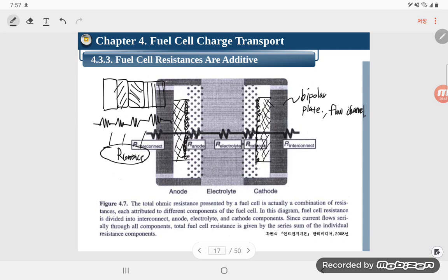And also the contact resistance is dependent on the compression pressure. So also when we assemble the fuel cell, the torque for the assembly of this single cell is a very important factor too. And when it comes to stack assembly, that is one of the most important things to operate, and to remove gas leakage to the outside.